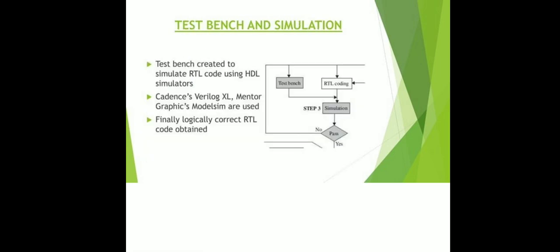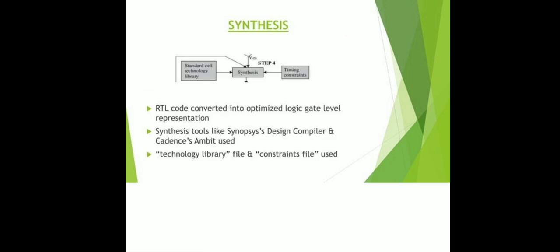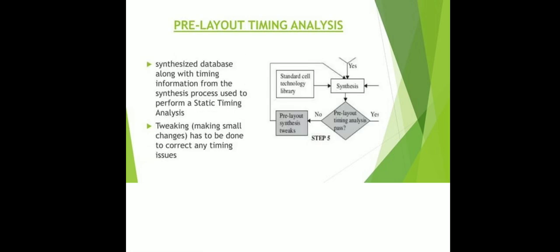Test bench and simulation. In the test bench, first we create and simulate an RTL code using the HDL simulators, using Cadence Verilog-XL or Mentor Graphics ModelSim. Finally it is logically corrected, and during the synthesis it is converted into an optimized logical gate level, and synthesis tools like Synopsys Design Compiler are used, and it is auto corrected.